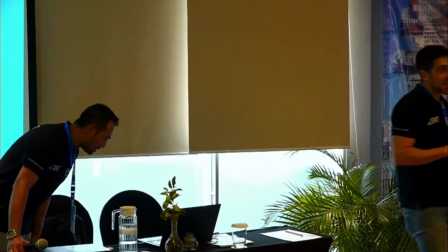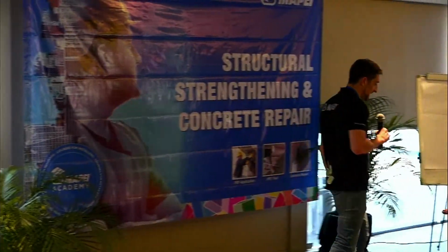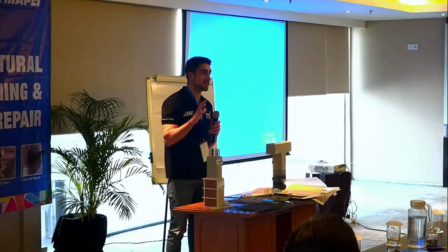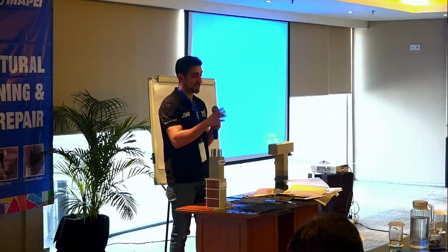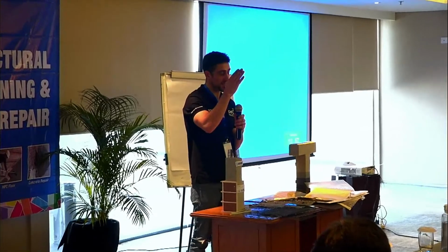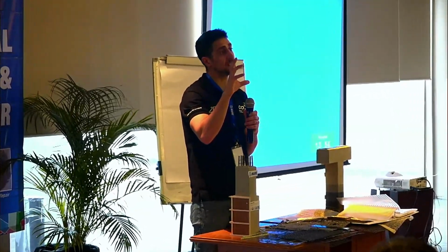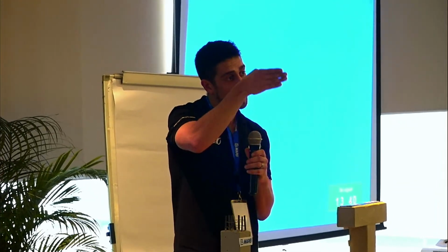No. Okay, basically, coming to the question, even if there are openings, it makes no big problems, because this kind of material is applied in vertical, okay? And the capacity of the system is linked also to applying the material above the structural element, because we are gluing these fabrics on the infill walls, but we have to extend this kind of material till the concrete element.